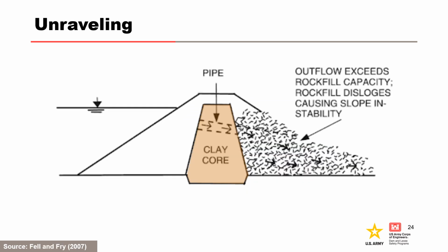Unraveling refers to progressive removal of individual rocks by large seepage or leakage flows through a downstream rockfill zone. In reality, rockfill has a large discharge capacity, and a number of dams have survived flows greater than 1 cubic meter per second.